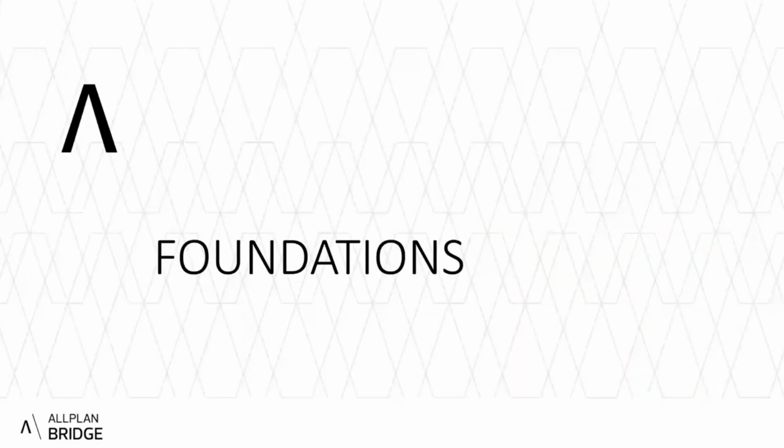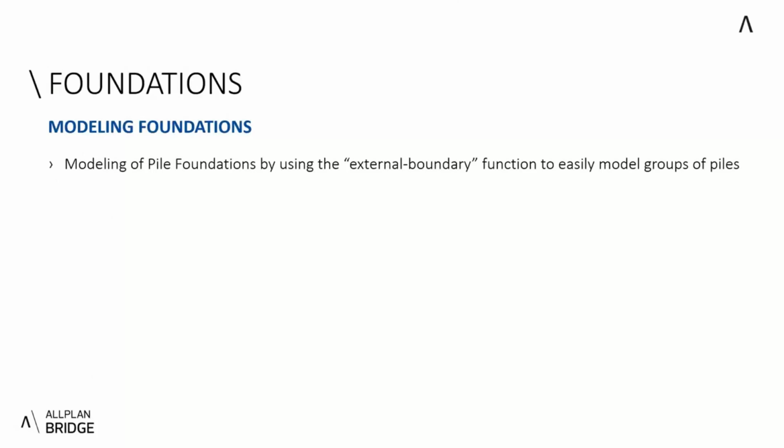The next step is where I'm going to share a few tips and tricks about foundations and how to make better use of modeling foundations. We know that sometimes our foundations have a lot of piles, and the process to create a pile is to create a circular cross-section for each pile.